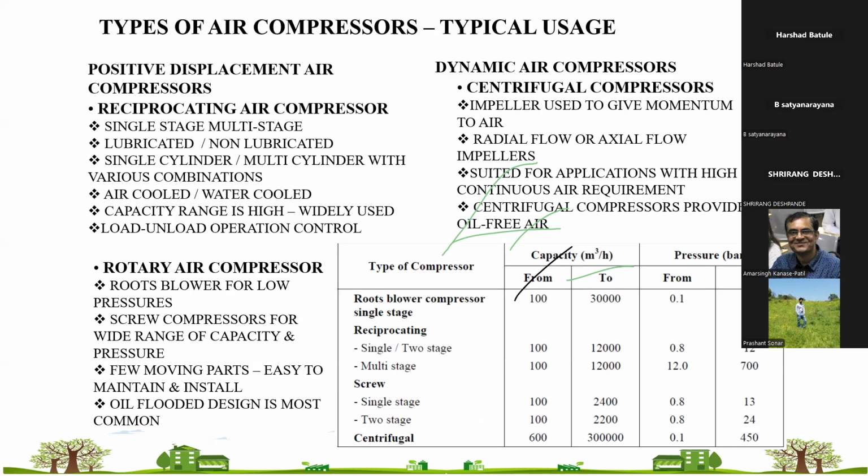There will be a technical comparison on the basis of specific energy consumption, what type of dryers you are using, whether it is an inbuilt dryer or an external dryer has to be fitted. What is the methodology of cooling of the air compressor? Because it will be either an air cooled compressor or a water cooled compressor.